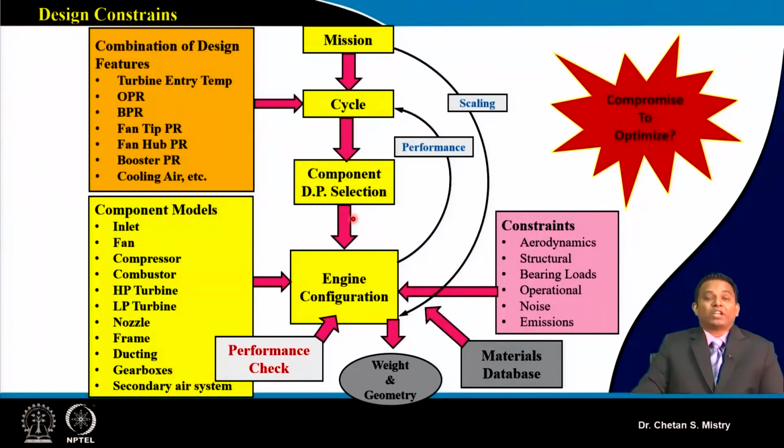The same is the case for the compressor. We expect the pressure ratio to be very high. If the pressure ratio is high, that means my per stage pressure ratio is very high, which gives me a reduction in length. Now, in order to meet that requirement, I may need to go with special kinds of aerofoils.